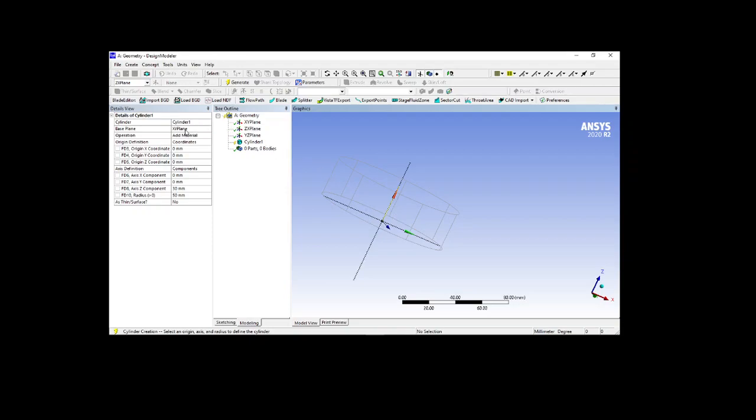If you want to change the plane from xy to zx or yz, you can do it here. So this is our yz plane. This is the y and this is the z. This is the global coordinate system. Are you able to understand now? It is now present at the origin; the center is located at the origin. If you want to give some more definition, if I give 20 here, it will shift the offset to y by 20.